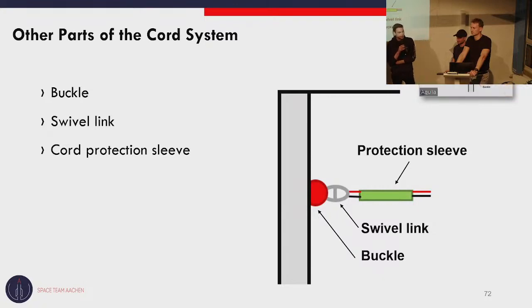So the testing is, let's call it a hybrid between ground testing and flight testing, because we designed a parachute sled which is pulled by a glider launch winch. So we can have a mobile test bench to which we attach the parachute, and we can measure force and wind speed. And combining those outputs of the sensors, we can do a couple of things. We can estimate the drag coefficient that the parachute has. This is then used to dimension the final parachute size. And also we can use this setup to test the deployment sequence. It is still not clear if we can actually have the nose cone deployment included in this test, but of course the main parachute deployment sequence can be tested this way. And we are currently planning to conduct these tests early next year.